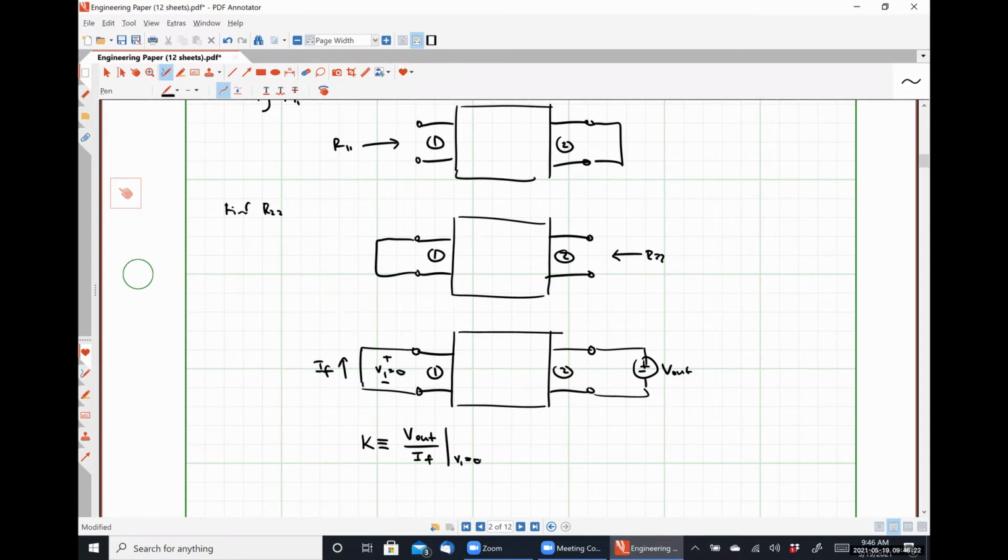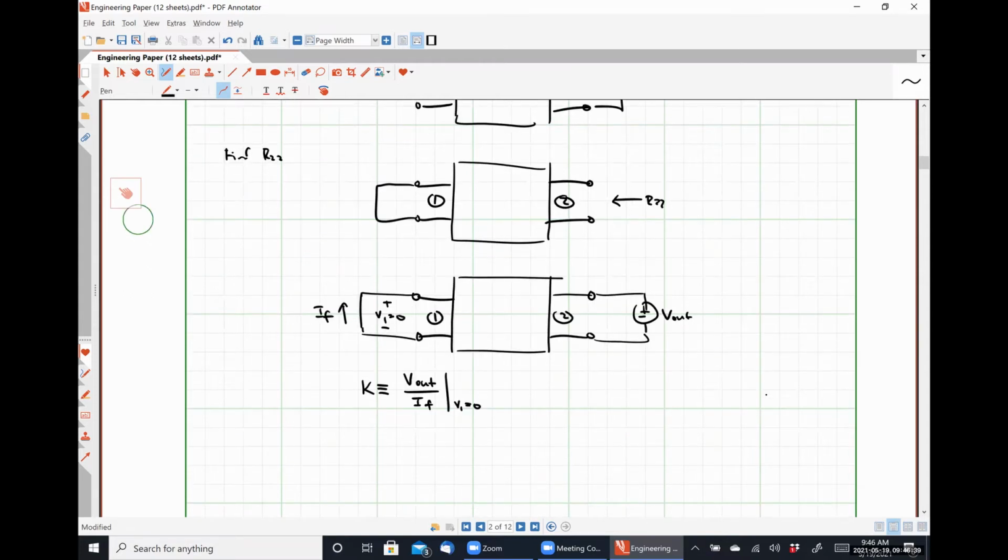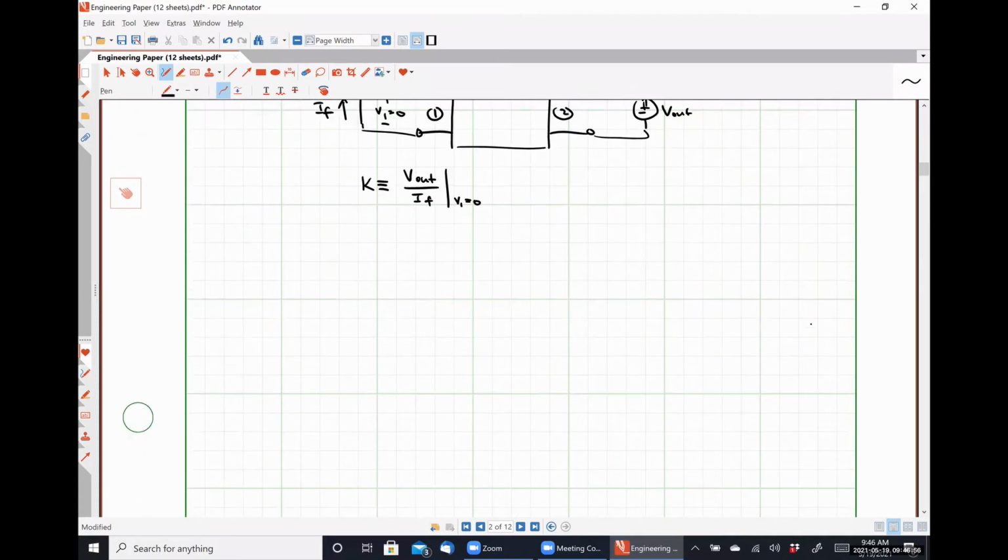So it seems like anytime we apply a current at our input, so when we have a current amplifier or a trans resistance amplifier, we're going to get negative feedback factors because of the way that we're accounting for things. So in order to have a negative feedback loop in our system, that means that the open loop amplifier is going to have a negative value for its gain. Otherwise, we're going to wind up with positive feedback, which is what we looked at a couple of things with on Monday.